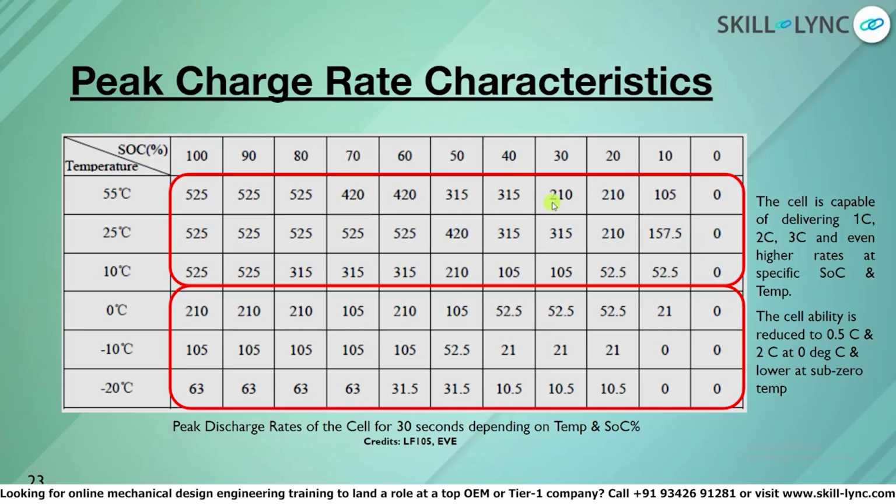So there's a C rate. When you are nearing 100%, you charge it slowly. When you are discharging and you are nearing 10%, 0%, you discharge with a lower current. So that is how you program your BMS accordingly, so that you don't abuse the cell much. You are operating the cell in a very good optimum operating zone, so that there is no abusing of the cell, which can give you the life cycles as expected.